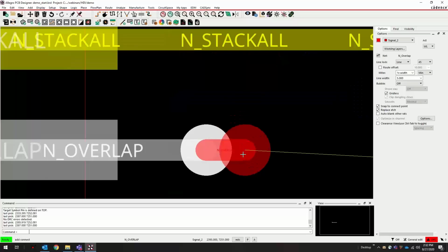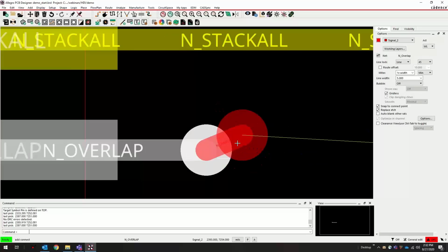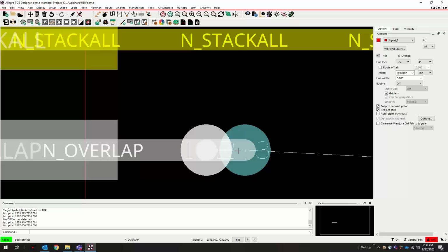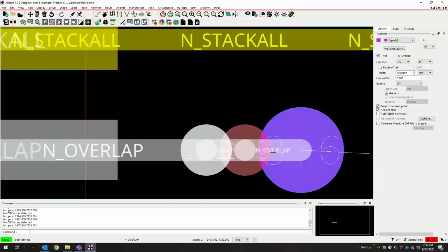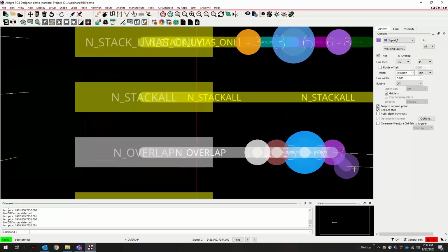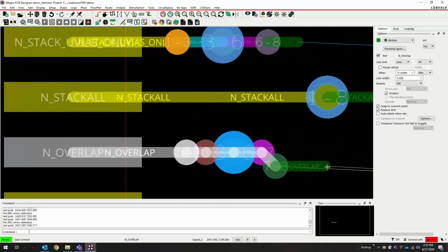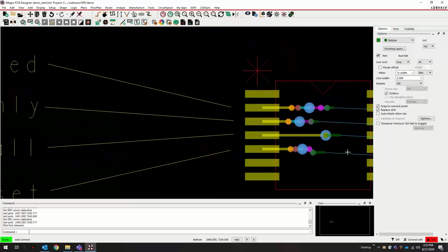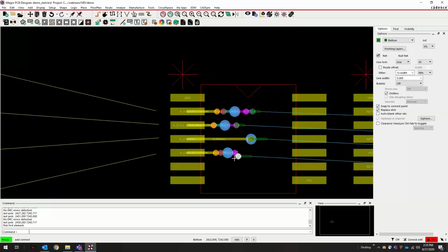You can see how it's set up so that the pad edge is actually next to the hole on those microvias and the core via. So here, as I place it down, I can place it down here if I want to. So this just shows the different techniques that can be used when you're routing with the blind and buried vias in the board to easily get from one layer to another.